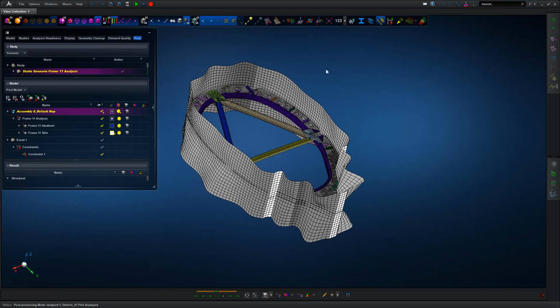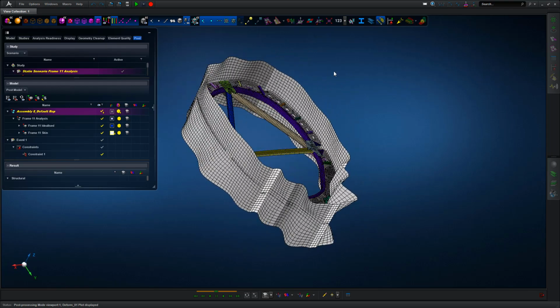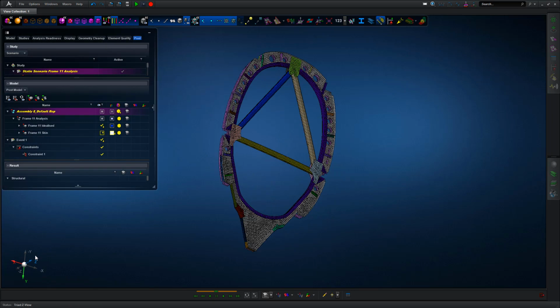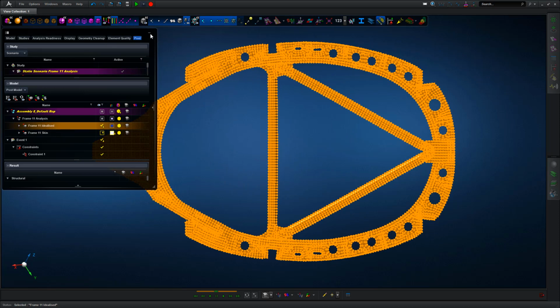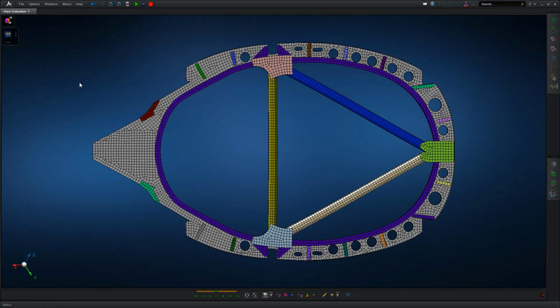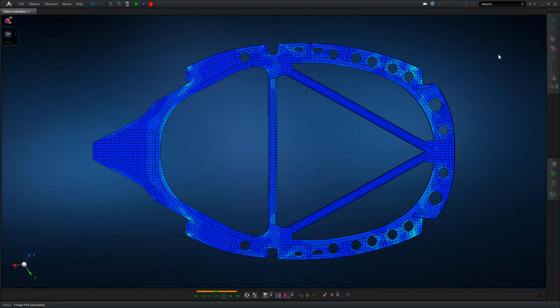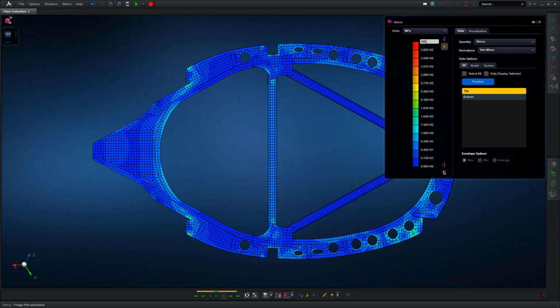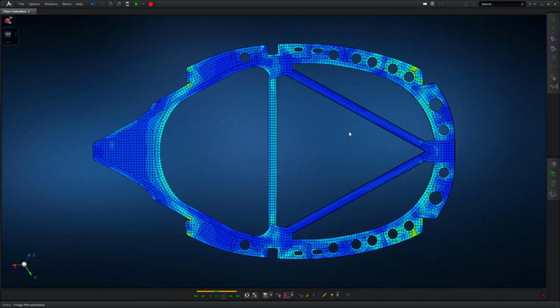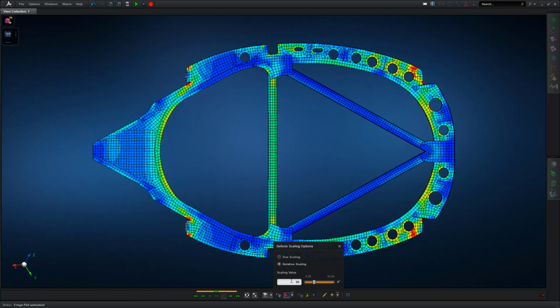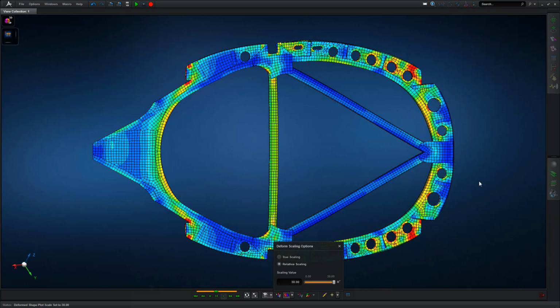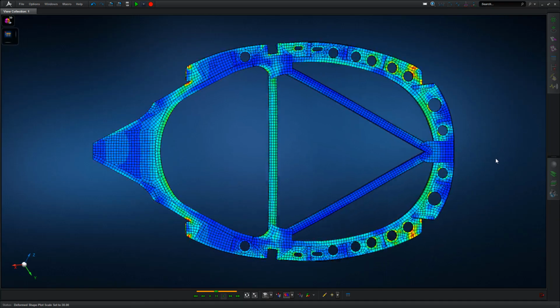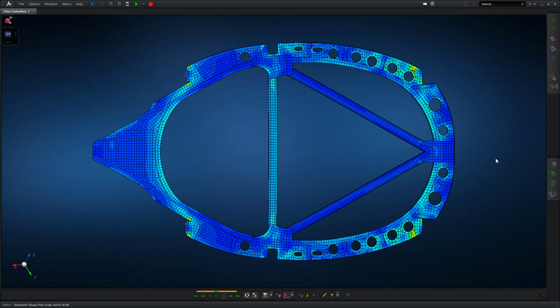So running through that, and again, we've got a very thin fuselage, so this is just an example, but it highlights the way the load transfer is moving into the fuselage frame. So taking the fuselage skin assembly out of view and post-processing based purely on the overall original sub-assembly, we can see by looking at the volumeized stresses and putting in a 200 MPa limit, which might be appropriate for the stress limit that we've got defined for the structure, and we can look at the major response and how the load is being tracked or distributed through the structure.